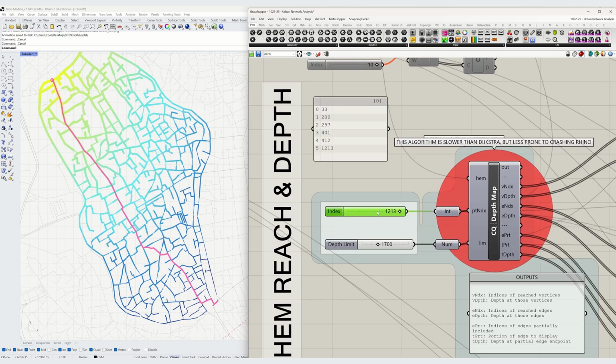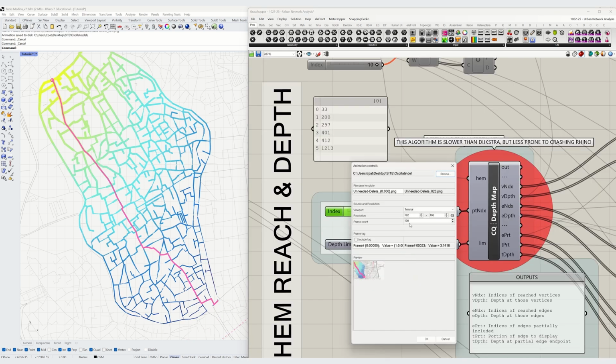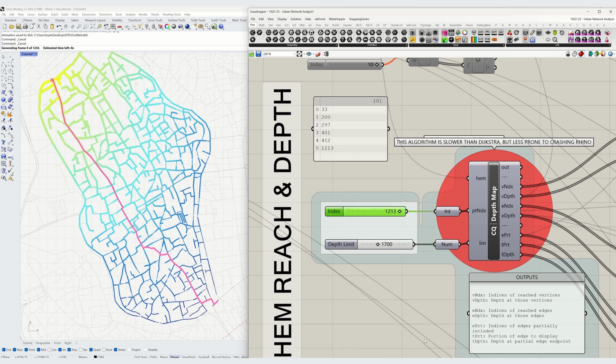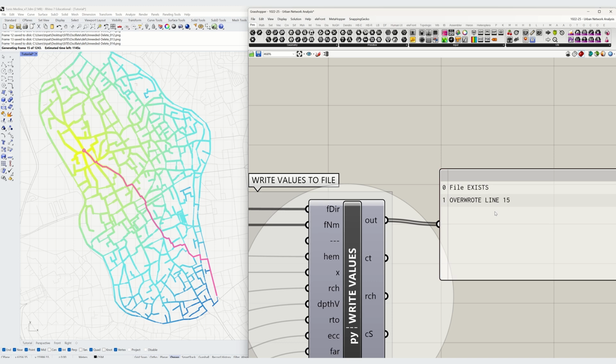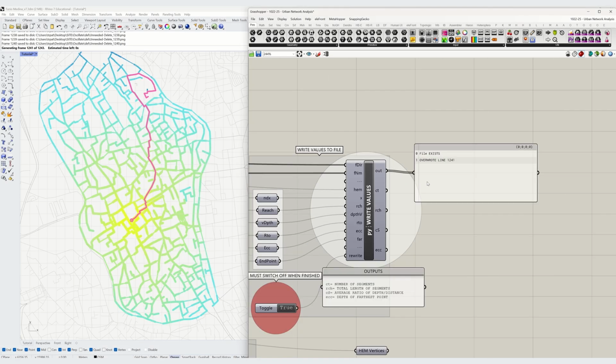Now animate the slider. It is not necessary to keep the image, so this can be low resolution for speedier processing. The frame count should also be equal to 1 less than the number of lines. After this is run, the CSV will be filled with the recorded values.